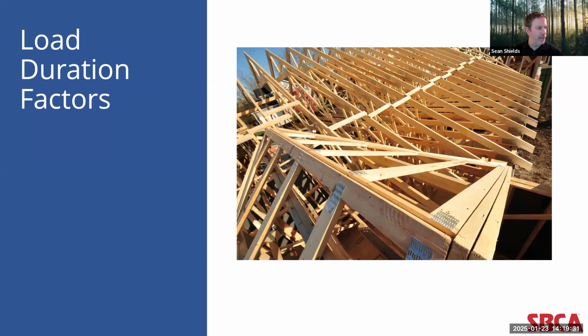Now, for those of you who live in mountainous climates, you'll know that snow stays on the roof for longer than 2 months at a time. But in general, snow loads are treated with this 1.15 load duration factor. There's then a 10-minute load duration factor of 1.6, and this is usually applied for seismic and high wind loads.